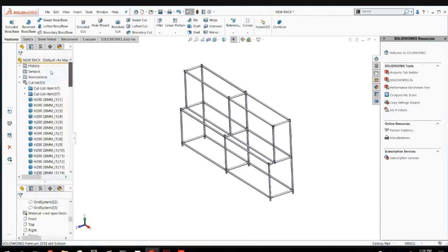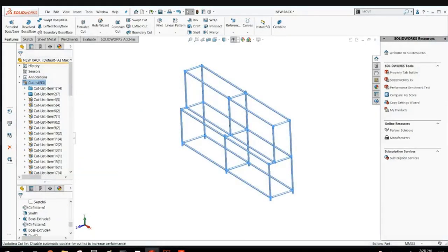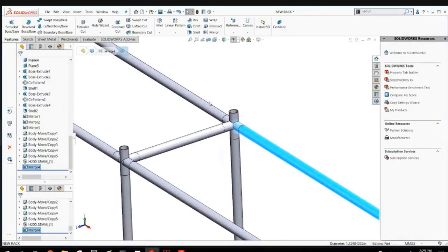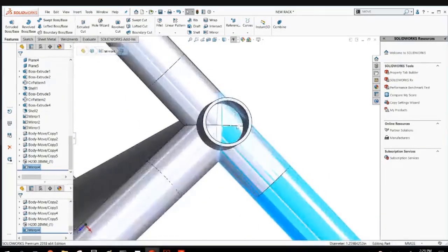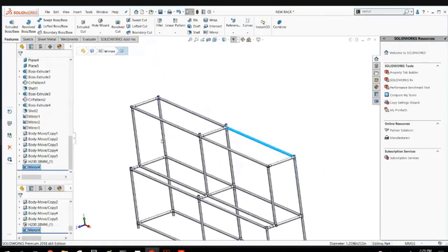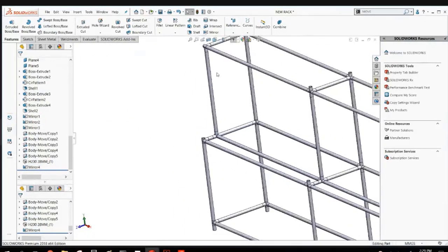And again, it's going to start keeping track of them. If I update the cut list, I can see how many individual cuts I actually need to do. Also, remember that this thing was giving me all these miters and stuff inside of this thing. You can also use commands to trim these up.